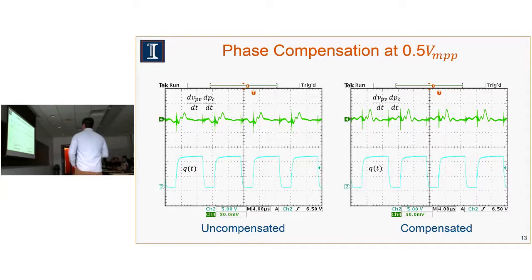But we can see that their product term has this positive and negative periodic effect, which you would get as those two terms move towards 90 degrees out of phase instead of the 0 degrees that we want. So this is the uncompensated product of the derivatives, and then this is the compensated, where essentially this negative portion was removed.